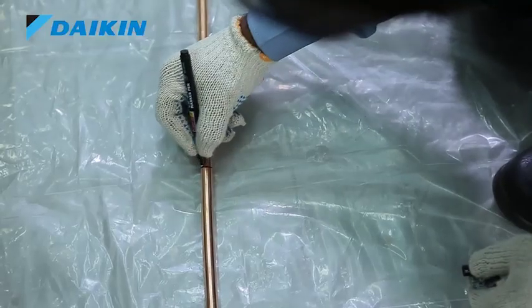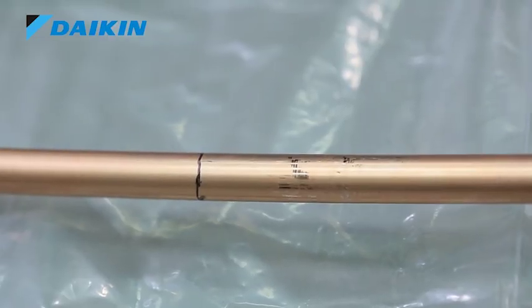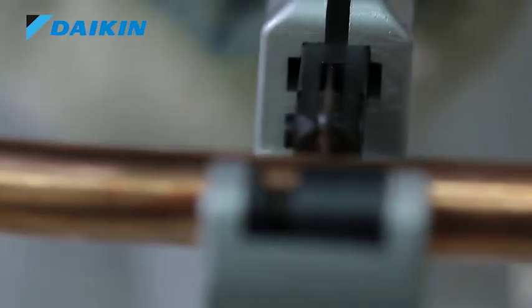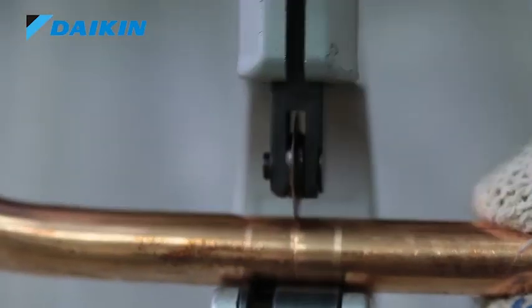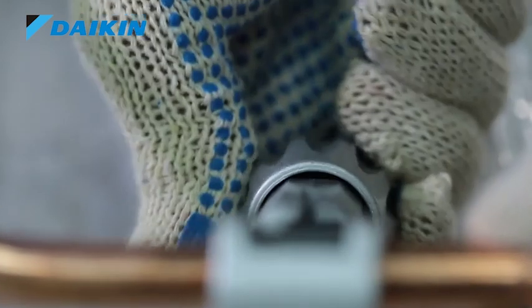In order to cut the copper pipe, mark the point on the pipe roll where the cut has to be made. Then, place this mark in tube cutter and press the cutter down slowly to prevent the deformation of copper pipe. The rotation of the tube cutter should be anti-clockwise, as clockwise movement will exert the extra pressure on the pipe, which may result in the deformation of the copper tube.